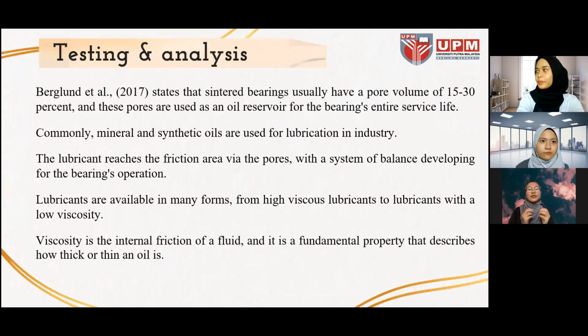Okay, I will continue for the testing and analysis for this self-lubricating bearing. When installing this bearing in the housing, its compatibility with the lubricant must be tested beforehand. Ruslan has stated that sintered bearings usually have a pore volume of 15 to 30%, and these pores are used as an oil reservoir for the bearings throughout the service life.